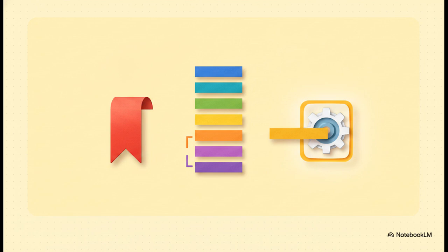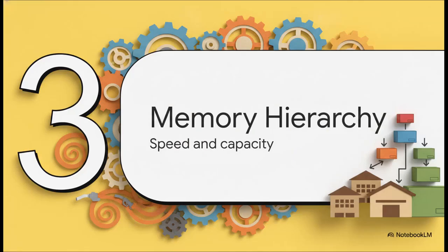The program counter, or PC, acts kind of like a bookmark. It holds the exact address of the next instruction that needs to be fetched. Meanwhile, the instruction register, or IR, safely holds the current command that is being executed right at that moment. Working together, these two ensure the CPU flawlessly keeps its place in your code, executing line by line without ever skipping a beat.